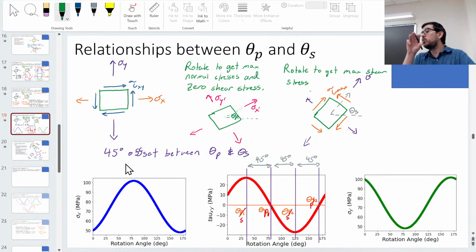And so when you do that, you're like, oh, okay, well, I've got the normal stresses in the direction. But if you're doing it for a ductile material, it actually fails because of shear. So you can look at those materials that are ductile, and if you look at the orientation 45 degrees, either from the vertical or from the horizontal, there are lines that form, and those are shear planes where the material actually fails, okay? And that's where the maximum shear stress is happening, at 45 degrees relative to that. Okay.